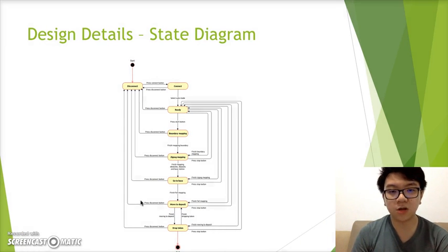And this is our state diagram for our auto mode. Initially, it is also in a disconnected state. When we press connect, it will go to a connect state. And then when you select auto mode, it will go to ready state. From here on, it can go to boundary mapping, zigzag mapping, or even go to base. It depends on what is already available on our map. If it has finished the boundary mapping, then it will jump directly to zigzag mapping. And it is the same when we press on disconnect button, it will go to disconnect state.